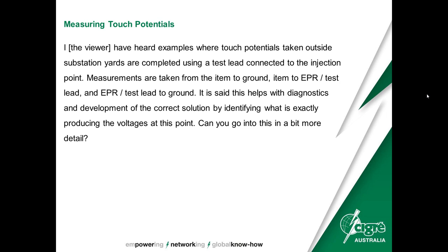Alternatively, this could be a low on high resistivity situation, and the substation voltage could be holding up out to 10 metres away from the fence, from the substation. And this fence may actually go hundreds of metres away down the side of a road, and the fence may be drawing in a remote voltage which is much lower than the EPR and lower than the soil voltage at that location. Now in that case, the ground is the high voltage and the fence is a lower voltage. So the same 500 volts is there, but which way was it caused?